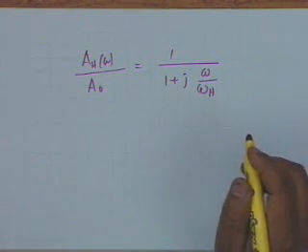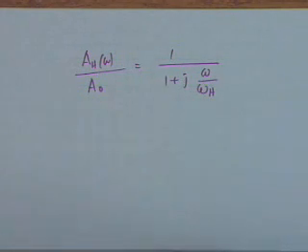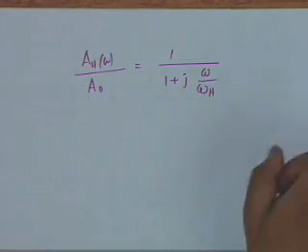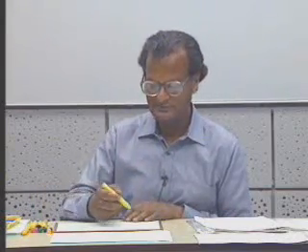Is that okay? There are no other capacitors determining the omega H. Why not? We had started with 2 capacitors. How come we have left with only 1? Because we ignored CC1 and CC2 and C, which have no business to show their faces at high frequency. C mu at the output circuit, we ignored its effect. Suppose we included the effect, what would have happened?